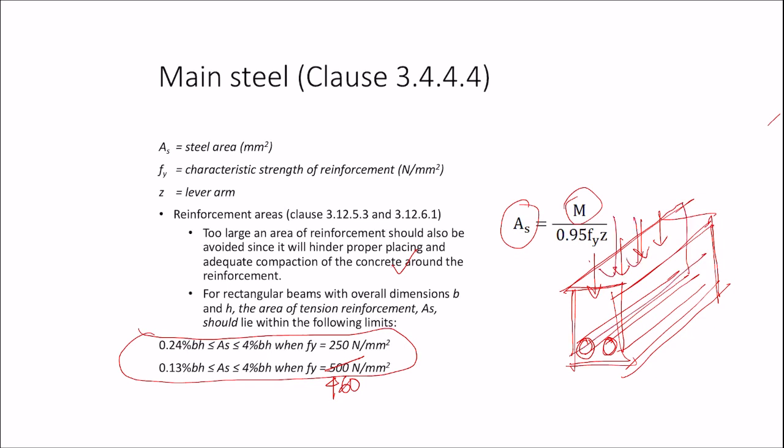If the size of the reinforcement is too big, okay, how is all the concrete going to settle in this bottom area? Because we do not put the formwork at the bottom first, then pour concrete at the bottom, and only after that put the bars and install the reinforcement at the side. No. We prepare the formwork first and then you put some spacers. Okay, then you will put in the concrete. How is the concrete going to fill all the voids at the bottom?